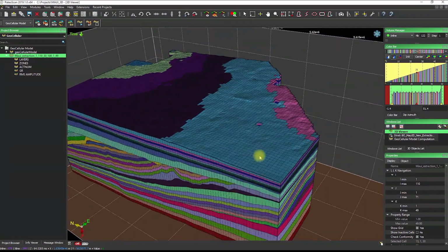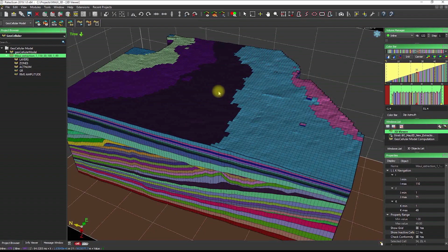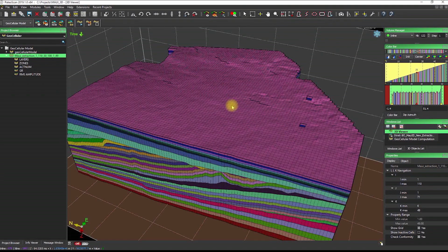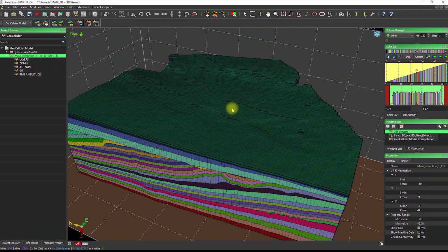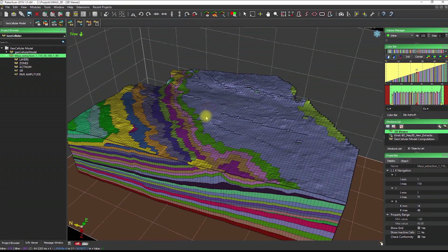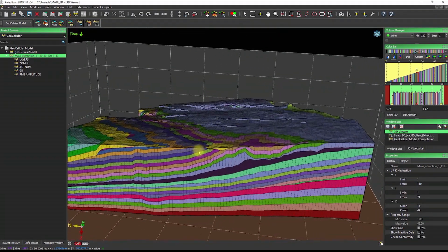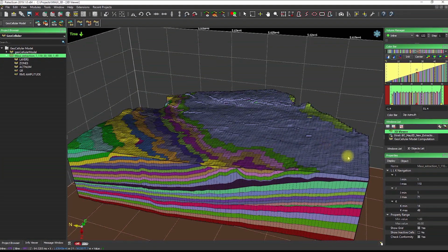Now if I want to scroll through the GeoCellular grid and visualize its geometry, I just have to select by double-clicking the top of my cellular grid and scroll through it, as if I were scrolling through a horizon stack. Scrolling through it, PaleoScan removes every layer of the GeoCellular grid, and I'm going to go through this until the erosional unconformity between the Miocene and the Pliocene, to be able to visualize here the top laps truncated on the unconformity.